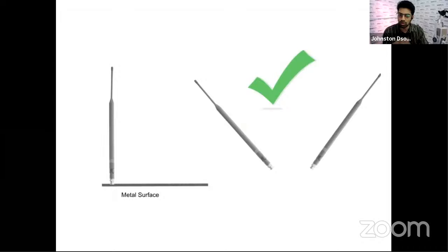Perpendicular metal surfaces, okay. Antennas 6 inches, 5 inches apart from each other, okay. If they're powered antennas, active antennas, at least 6 feet. Now, another thing is, whenever you're mounting, if you're in a live show, you'll be using in-ear monitors and you'll be using wireless microphones also.